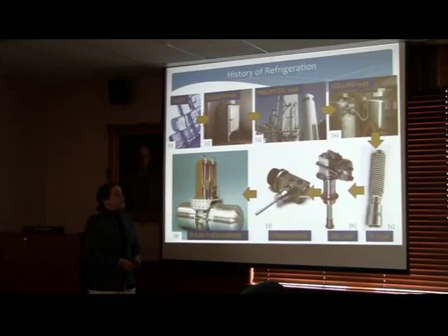And that led to the development just a few years later of the Joule-Thomson cryocooler, whose applications today work all the way from small microcooling to the liquefaction of air and helium. And then around the same time, you get all three of these: the Stirling cryocooler, the Gifford-McMahon, and the pulse tube cryocooler. The big difference between the other cryocoolers and the pulse tube cryocooler is that in the actual pulse tube, there's not a displacer between the hot and the cold end. It's a gas piston, so it's just a piece of gas that will not move out of the pulse tube.